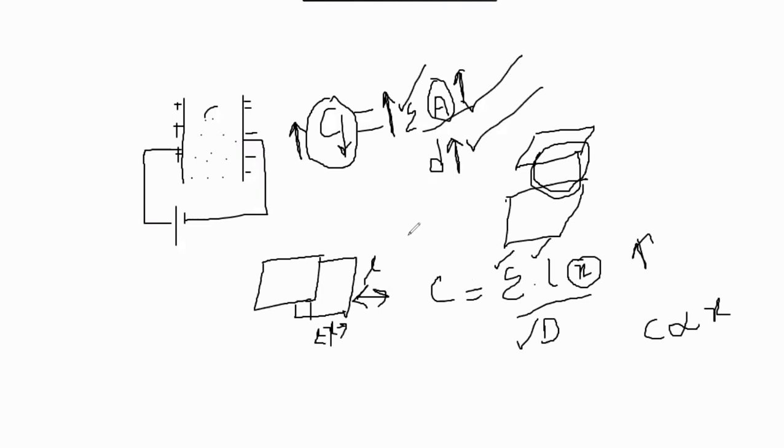So like the RTD and strain gauge, if the capacitive transducer is configured with a Wheatstone bridge circuit, displacement is the input quantity, and it causes a change in capacitance. Obviously the bridge will become unbalanced, so we get an output voltage. The output voltage can be calibrated in terms of displacement.